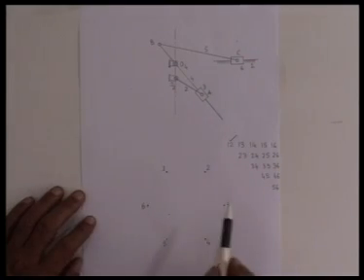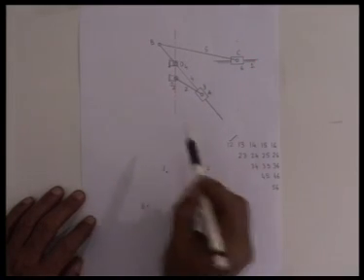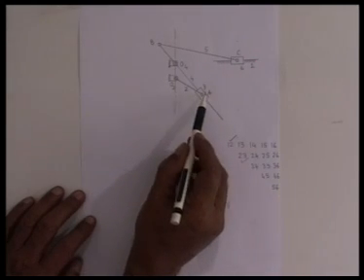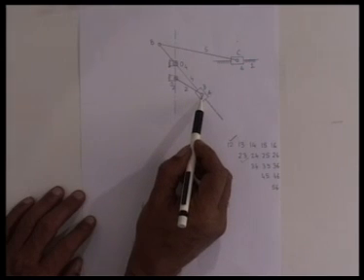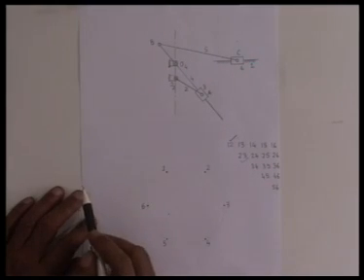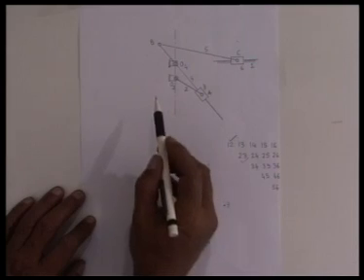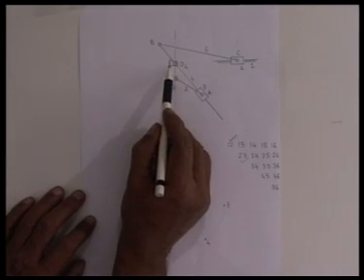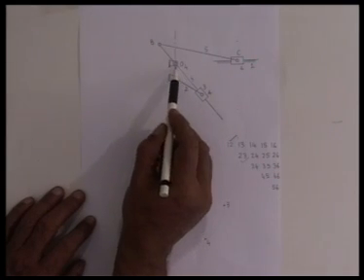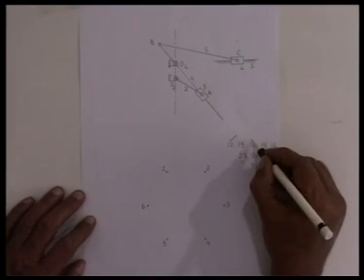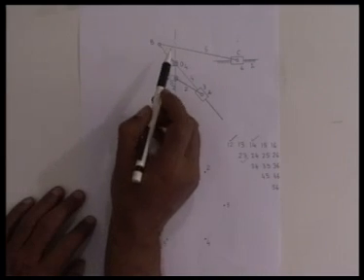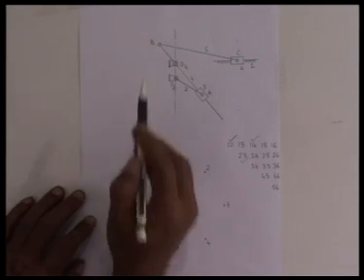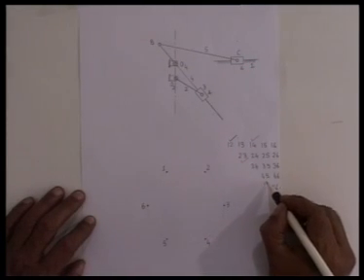Similarly, 2, 3 is easily located at the revolute pair connecting link number 2 and 3, that is at this point A. 1, 4 is easily located at O4 because that is where the revolute pair between link 1 and link number 4 is. Link number 4 and 5 are connected by a revolute pair at B, so 4, 5 is at B.